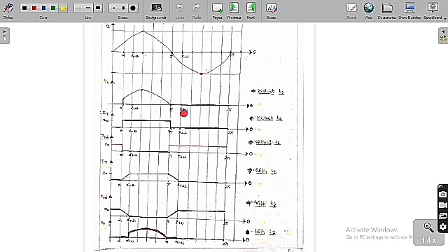The freewheeling diode is going to conduct. That is the meaning of this one. So now let me assume the load is having a constant current. So the load is having a constant current, therefore simply from 0 to pi. From 0 to pi also, as the load is having a huge amount of current.